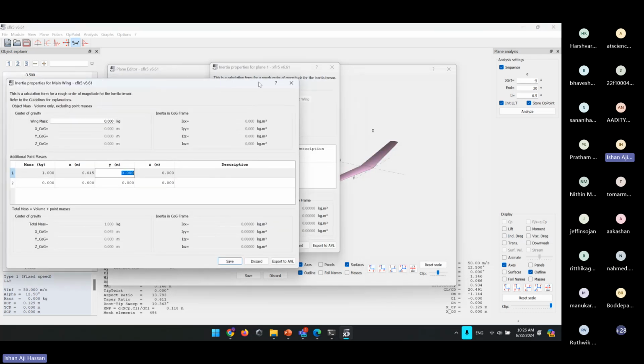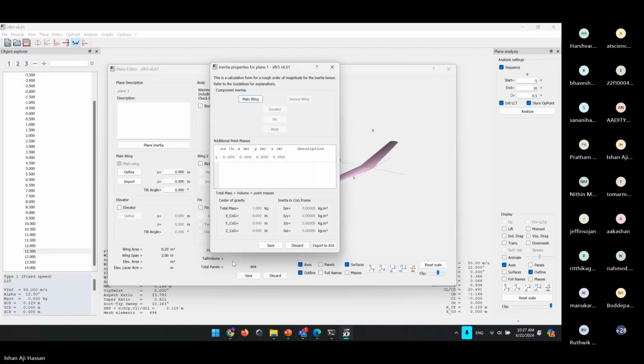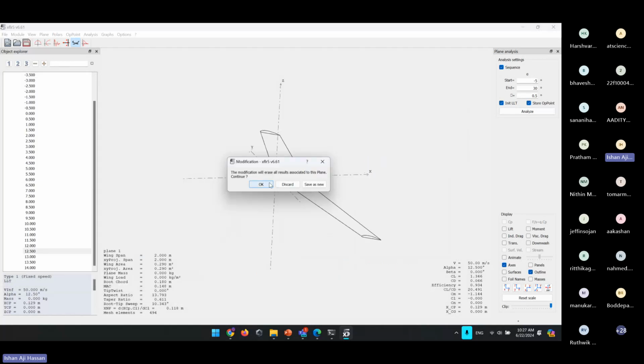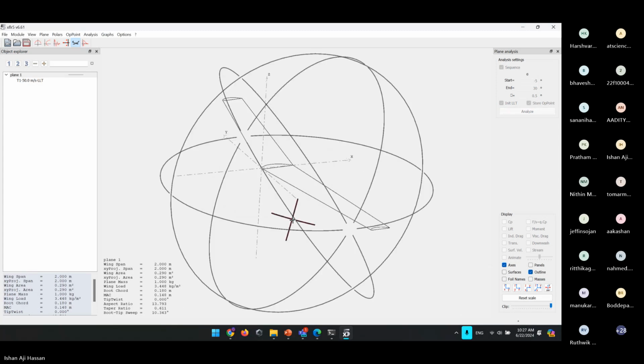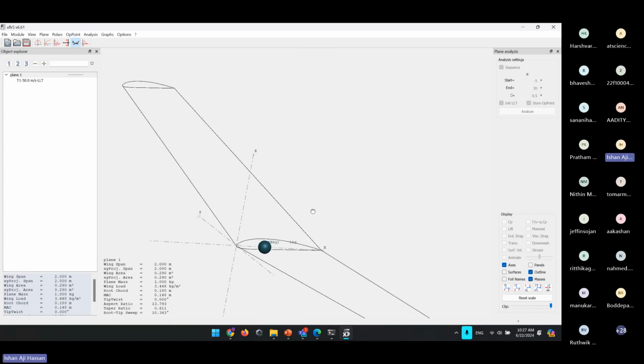That is simply because our wing is not uniform. Our wing has two sections that are entirely different. If it were a rectangular wing, it might be exactly 0.045. But I think you might have to move it a bit further back here, 0.06. And you can just save that, and that'll give the wing some inertia. You can click here to see the masses under display again.